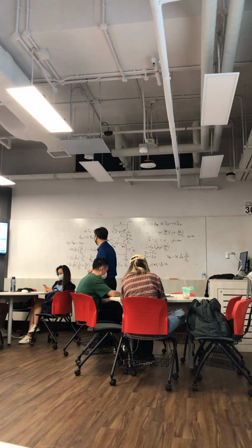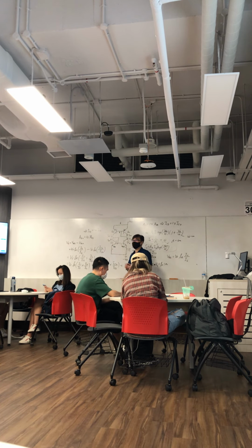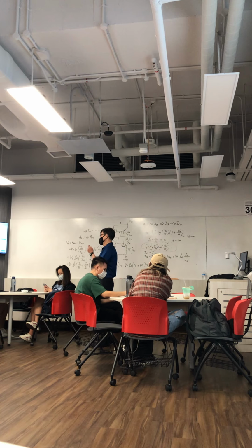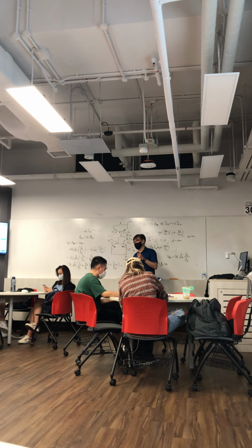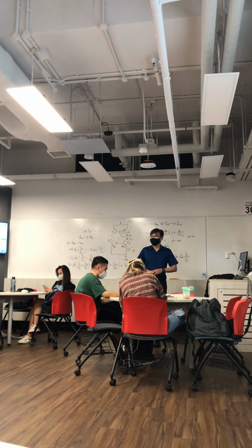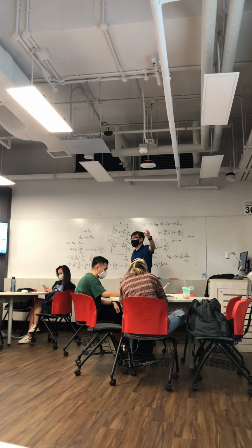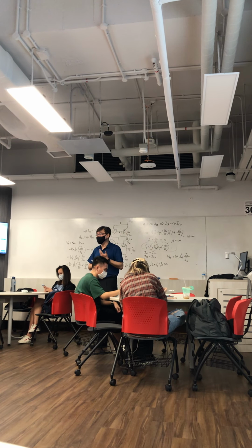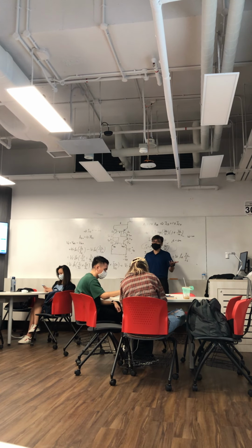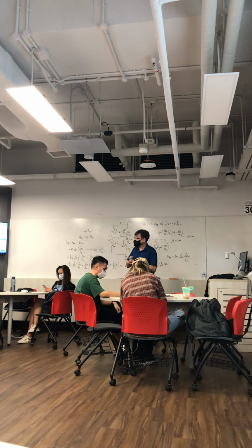Okay, I want to take this opportunity to show you a solution. At the same time, I'm going to tell you why this circuit is important in solid state circuit electronics: we can use it for thermal sensing. Today in all your CPUs, very smart designs can put a lot of these transistors and resistors in to sense the temperature, so that they can find whether there's a hot spot, and then cool down or shut down that part, and so on. Otherwise, you cannot put it into an IC, and then you cannot sense temperature on the IC directly. It's difficult to do all this kind of thermal management.